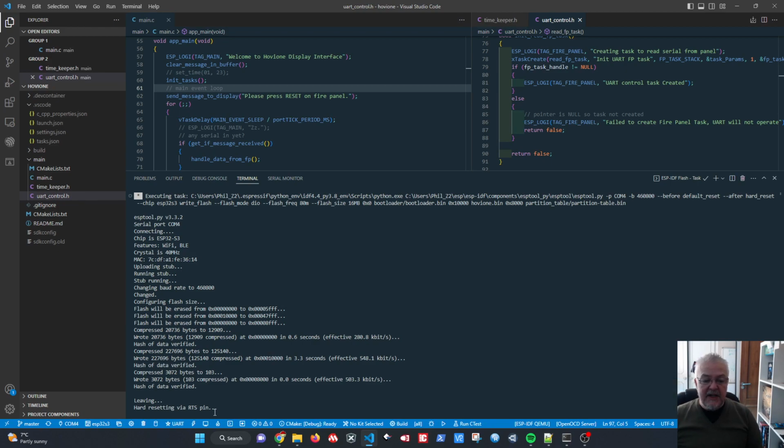I'm not using the build flash monitor because when you use the build flash monitor, this output here is lost, it's dumped, and you get the monitor. We need this information here, because this is using a built-in flashing tool. You can see here's the command. It's executing this command, esptool, the Python application, with the same COM port for the board it's using. And there's a couple of flags set: the mode, which is DIO, and the frequency, which is 80 megs. These are all very important.